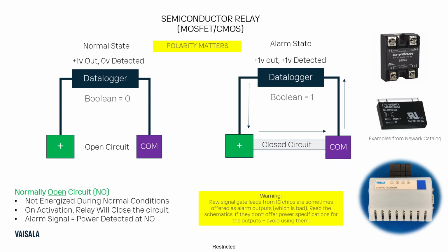And one note on here is some things will say that they have an alarm output, but they don't actually have a relay in the circuit. I've seen it many times where they put half the electronics in there. They'll have the logic chip inside the motherboard that has an alarm output, but these are not connected to a real isolated relay, where it's isolated from the electronics, and you have a truly separate circuit that's independent of the device that turns on and off. You have to read the schematics closely when you're working with anything that doesn't have a real relay on it.